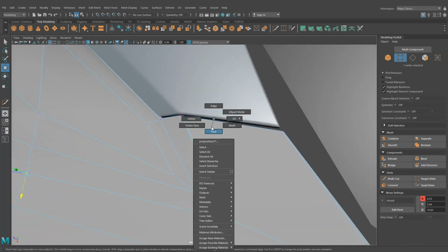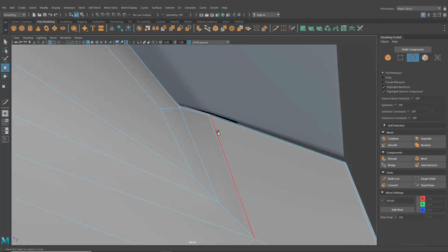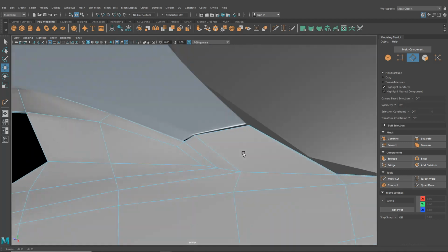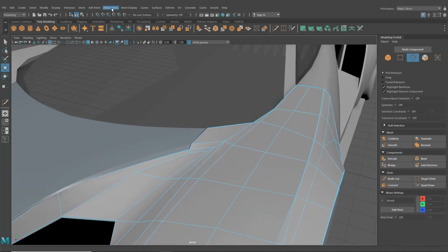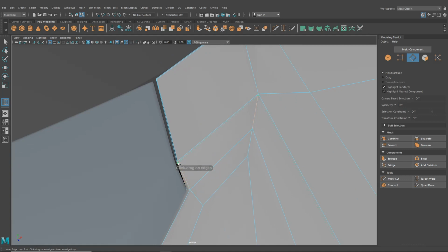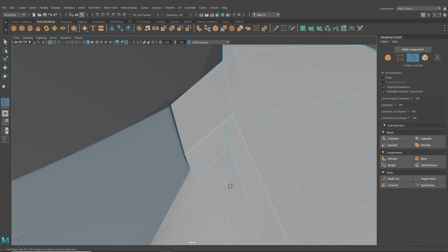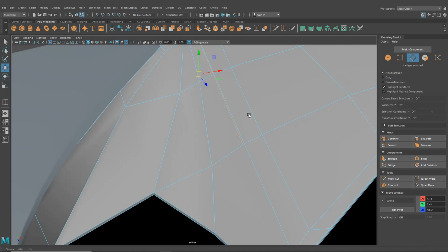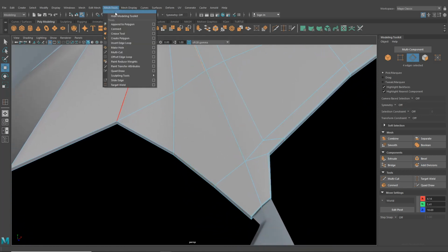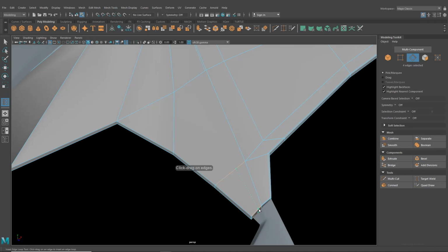What we'll also do is let's get rid of what we added in the last episode. I'm going to double click on this line here. I'm just going to hold down Control and hit delete because I don't think we're going to want that anymore. What we are going to want to do is I'm going to drop an edge loop here, and this time we're going to go in this corner. And let's just double check as we move down here. We've stopped there because of this angle that we have here. So we'll drop another one in this lower section as well.